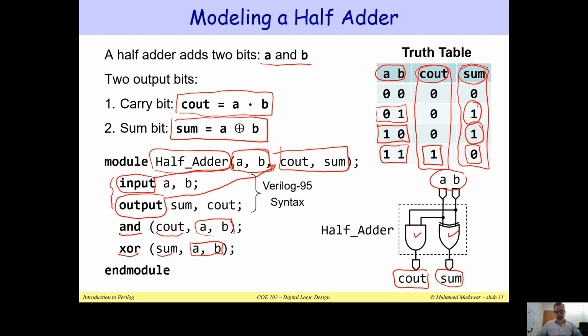This is very simple. Now, when we get the carry out, and I would like to add, let us say, two numbers in binary, this carry out is propagated. It becomes the carry in of the next bit. So when you are adding multiple bits, suppose I would like to add 8 bits plus 8 bits, as we had seen at the beginning of the semester, the carry out is propagated to become the carry in for the next bit.